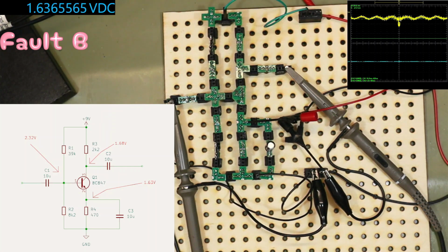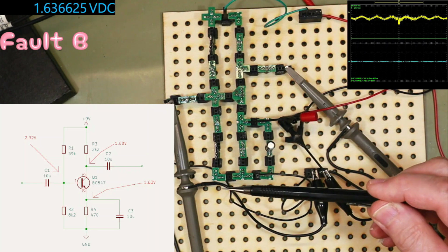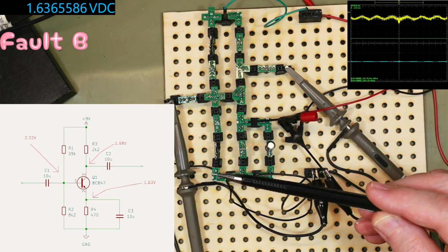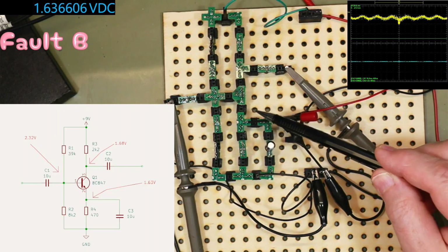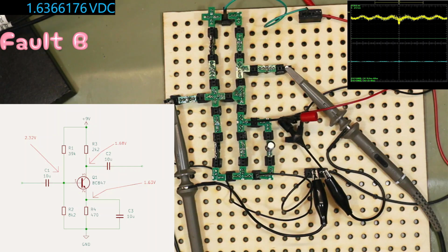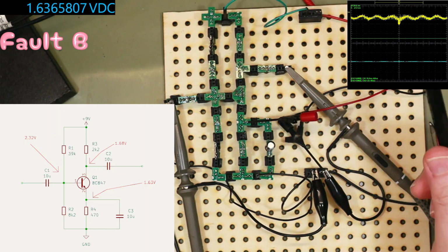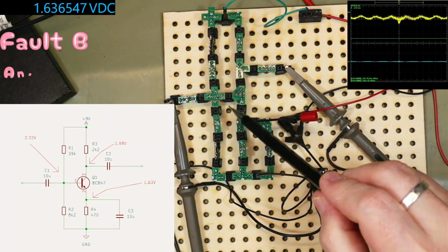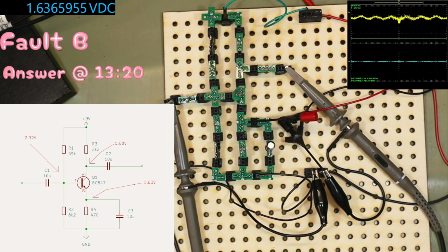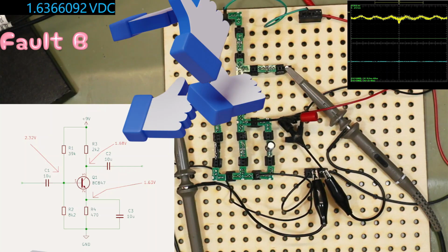saturated. And to give you the clue that it's fully saturated, look at the voltage drop across it. 0.05 of a volt, 50 millivolts drop across that transistor. That transistor is fully saturated, and so it's also affected the input signal. Look up there, it's dropped a bit because the impedance around this area has dropped, and it's affecting the signal generator. But what could be causing that? Why has the base gone so high?